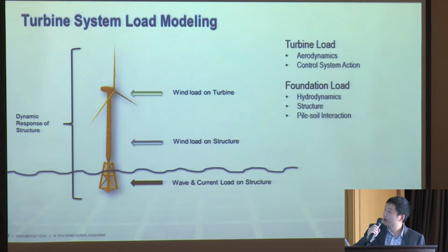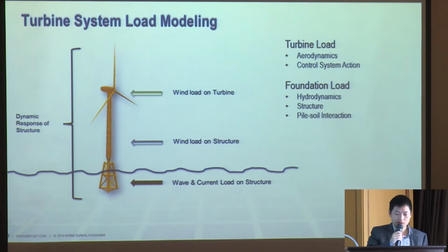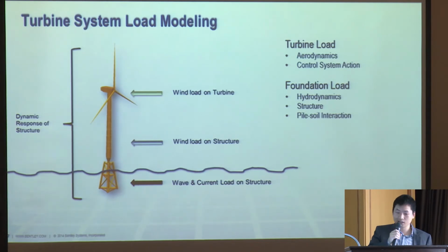And when you calculate the turbine load, you need to include the aerodynamics and the control system action of the turbine system.